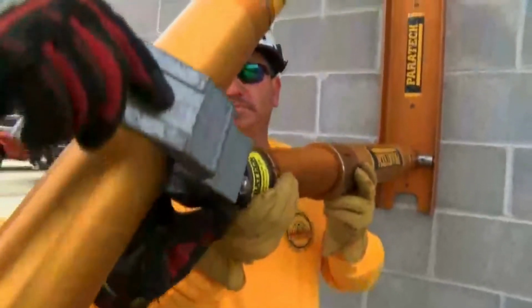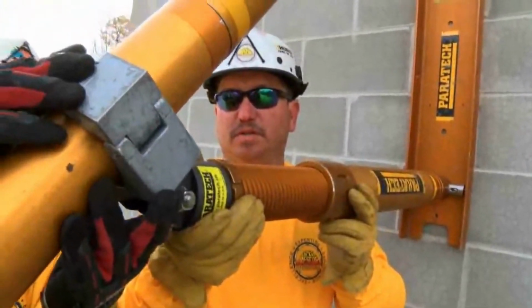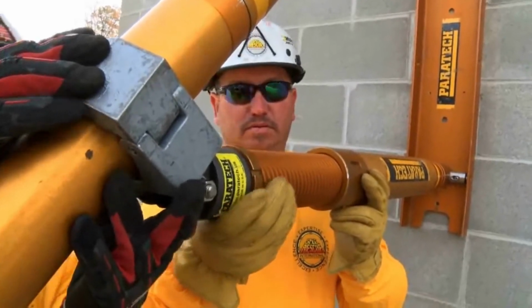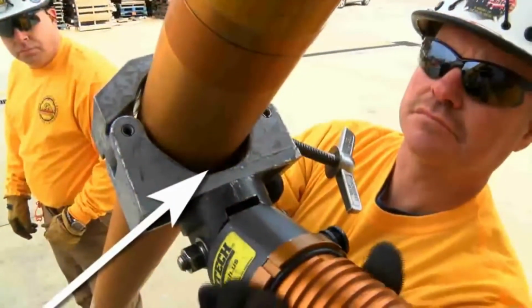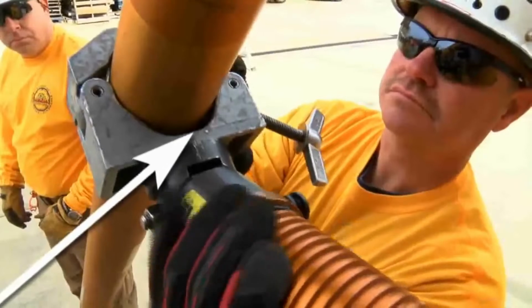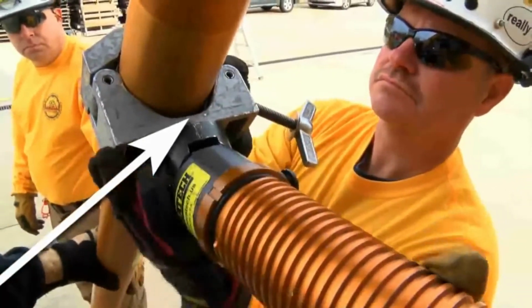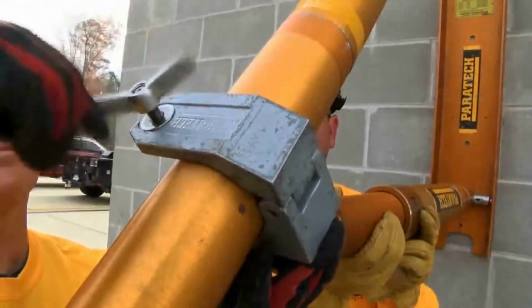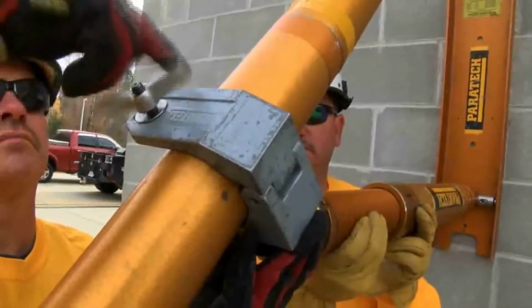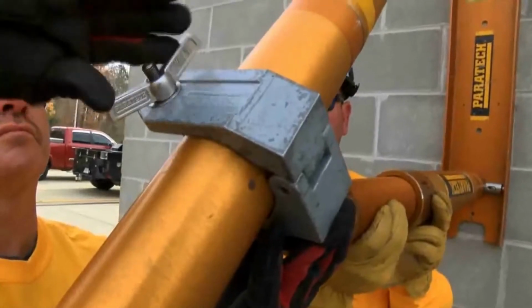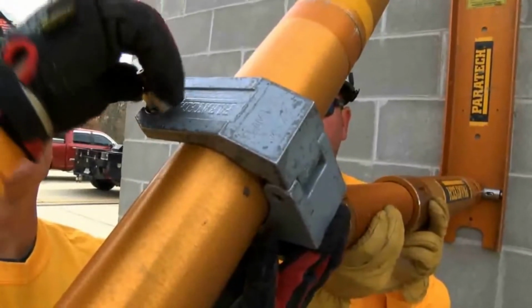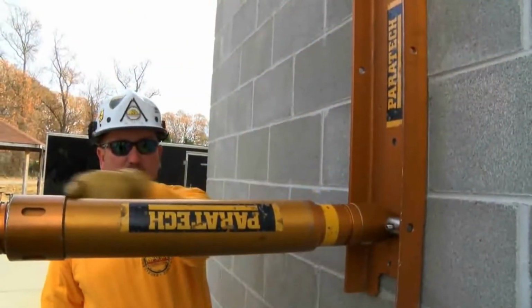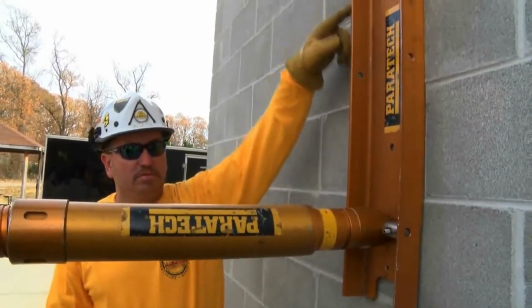Now attach the brace to the raker length. Bring the B23 up and make a 90-degree angle. If it is not exactly 90 degrees, spin out the piston to make the clamp tight so the gap in the back is filled. When tightening the butterfly nut on the clamp and clevis, make sure the washer is on top of the clamp. Turn down the butterfly screw hand tight. Make sure there is a 90-degree angle between the wall plate and the brace.